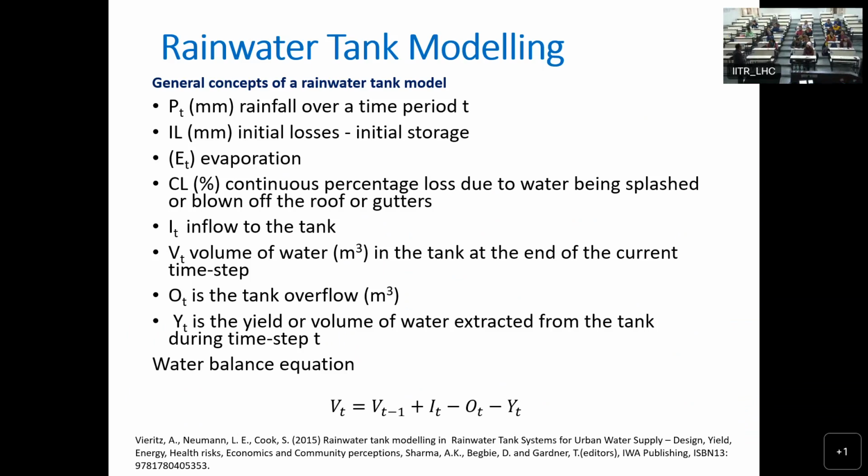So these are the benefits of using such software, which will give you a better outcome. They will give you a better estimation of the rainwater capacity based on the daily rainfall pattern, the demand, and the size. Then you have an option to select whether you want to provide a tank with 90% reliability, meaning 90% of the time the water is available from the rainwater, or 90% of the demand is available from the rainwater.